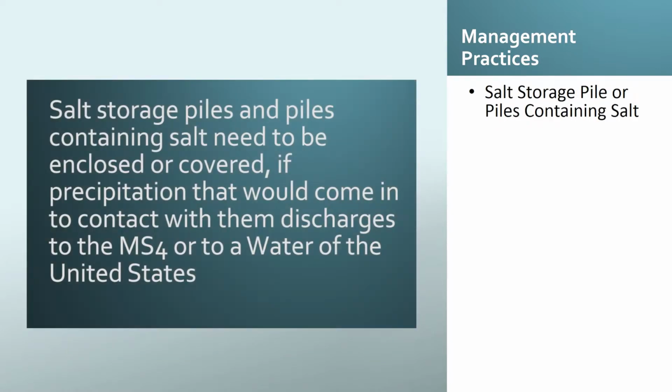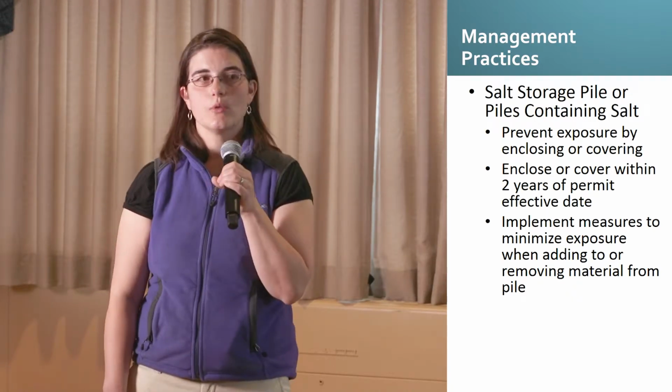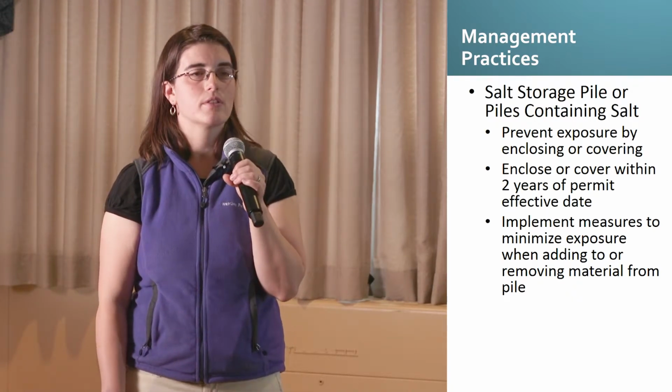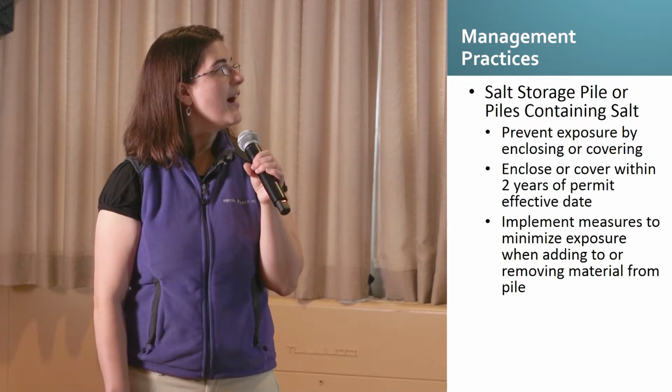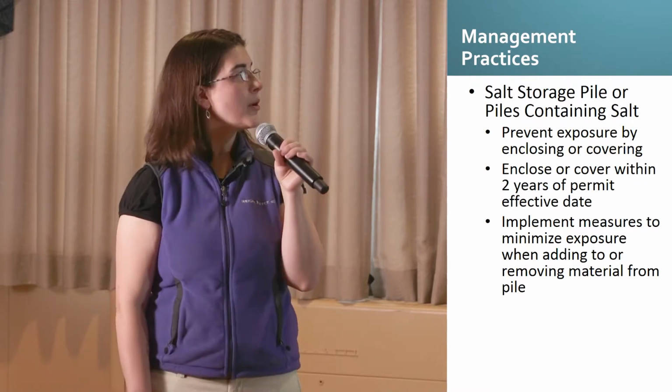Salt storage piles and piles containing salt need to be enclosed or covered if precipitation that would come into contact with them discharges to the MS4 or to a water of the United States. You should prevent the exposure by enclosing them, putting them in a shed or some other enclosure. And they need to be enclosed or covered within 2 years of the permit effective date.